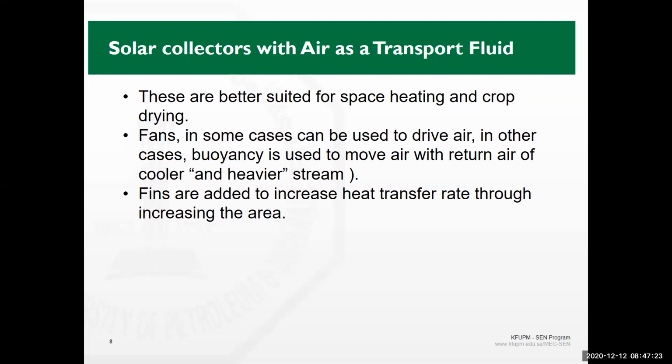You may use fans or blowers to drive the air in. Using fans is costly because fans require more energy compared to pumps. However, there are some collectors that use the buoyancy effect. As the air is heated, it becomes lighter and tends to move upward. As the air cools, it tends to move downward.